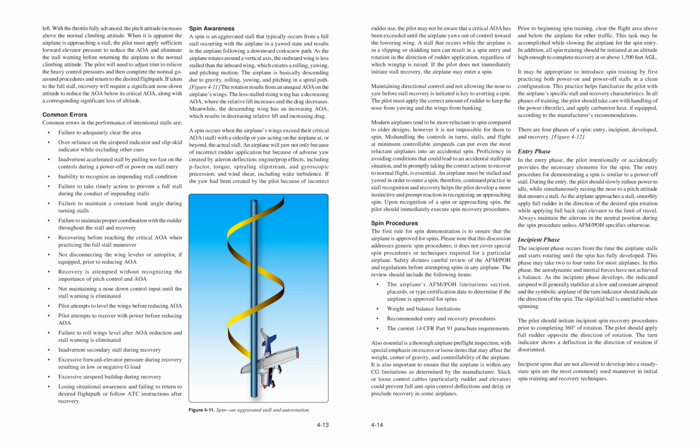inadvertent accelerated stall by pulling too fast on the controls during a power-off or power-on stall entry, inability to recognize an impending stall condition, failure to take timely action to prevent a full stall during the conduct of impending stalls, failure to maintain a constant bank angle during turning stalls, failure to maintain proper coordination with the rudder throughout the stall and recovery, recovering before reaching the critical AOA when practicing the full stall maneuver, not disconnecting the wing leveler or autopilot, if equipped, prior to reducing AOA.